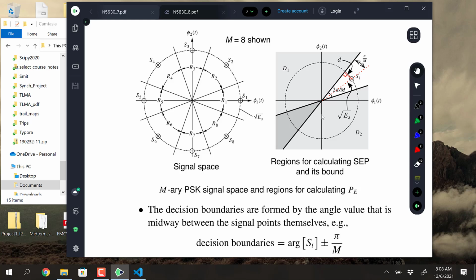We have 4 different locations we can be in for QPSK, right? So if we make our bit detections on the in phase, we have a threshold detector, and we detect whether it's on the positive or negative real axis. And then for the quadrature, we do the same thing. And I'm now rotating the whole thing by 45 degrees. My other graduate student said, why is QPSK always shown with the 4 points like this rather than rotated? Actually, when you demodulate QPSK, you demodulate it with it rotated, because you want to simply look at the sign of the real part, and then the sign of the imaginary part, which gives you the 2 bits.